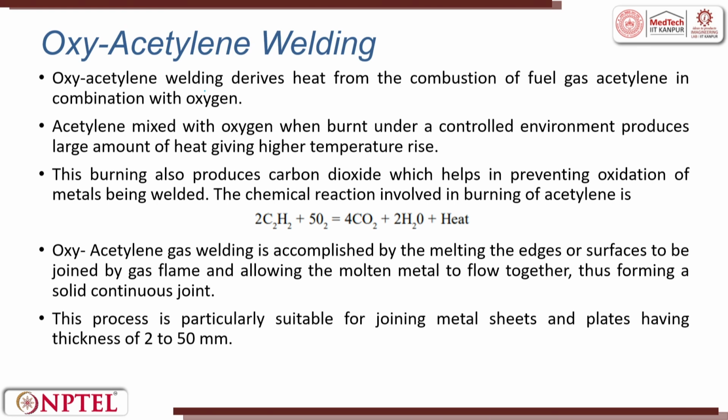Oxyacetylene welding derives heat from the combustion of a fuel gas, acetylene, in combination with oxygen. The acetylene mixed with oxygen, when burnt under a controlled atmosphere, produces a large amount of heat, giving a high temperature rise. This burning also produces CO2, which helps in preventing oxidation of the metal during welding. So, acetylene plus oxygen gives you carbon dioxide plus water plus heat. So, this now becomes a protecting shielding layer.